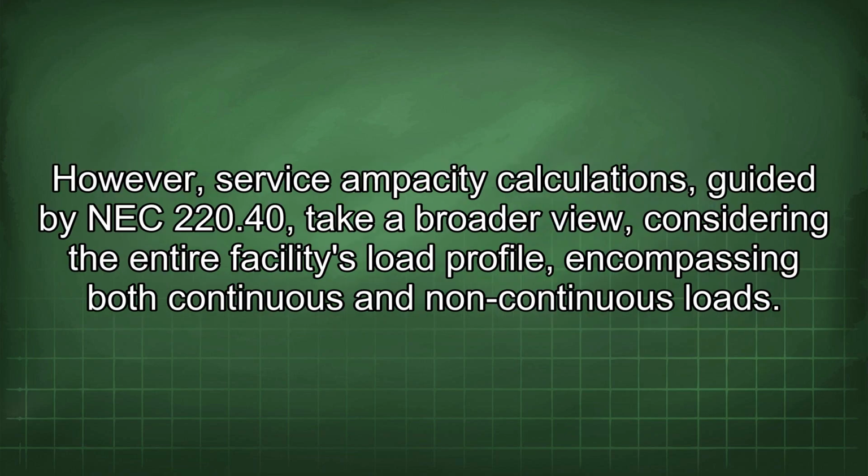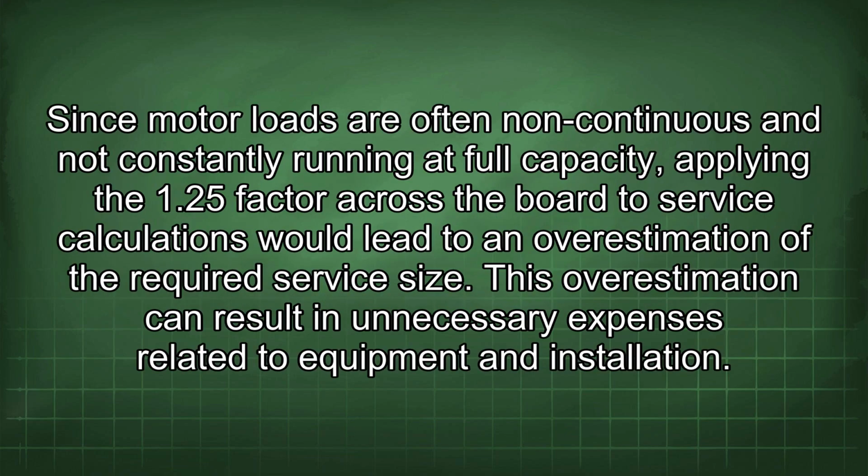However, service ampacity calculations, guided by NEC 220.40, take a broader view, considering the entire facility's load profile, encompassing both continuous and non-continuous loads. Since motor loads are often non-continuous and not constantly running at full capacity, applying the 1.25 factor across the board to service calculations would lead to an overestimation of the required service size. This overestimation can result in unnecessary expenses related to equipment and installation.